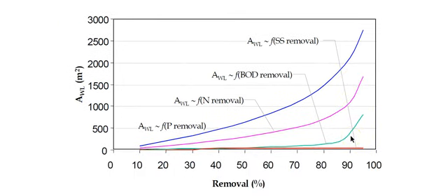Here we have percent removal for the different parameters based on what the model says for natural treatment systems, the wetlands. The simple equations we saw above. So as an example, let's say your requirement is nitrogen removal. And let's say the government says you need 70% nitrogen removal, then given the flow here, we can go up to the line for nitrogen removal and we go over here and we get about 500 square meters.